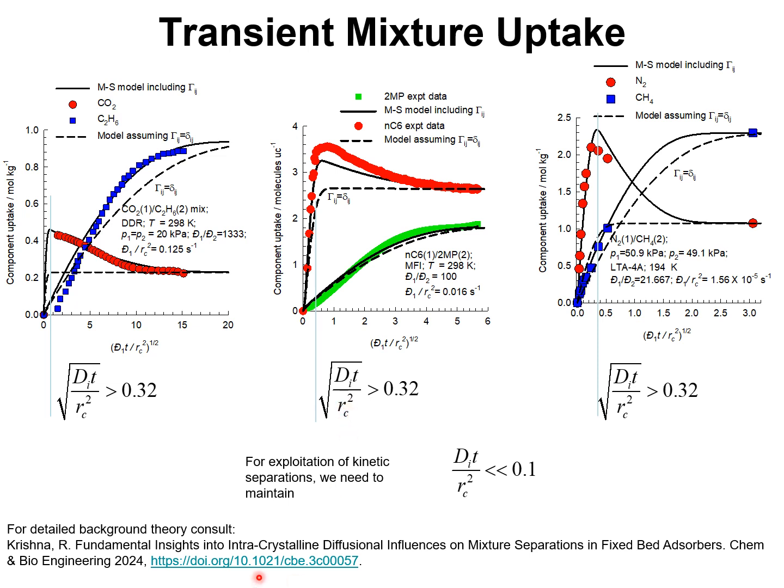In this paper that is not yet online, I argue that for kinetic separations to be effective, we need to operate at conditions wherein the diffusional time constant multiplied by the contact time in the fixed bed adsorber is smaller than 0.1.